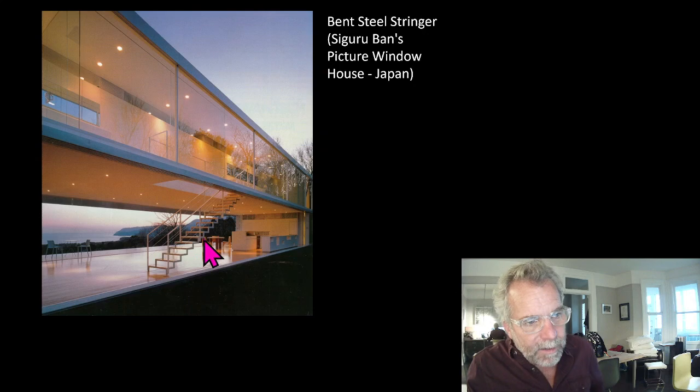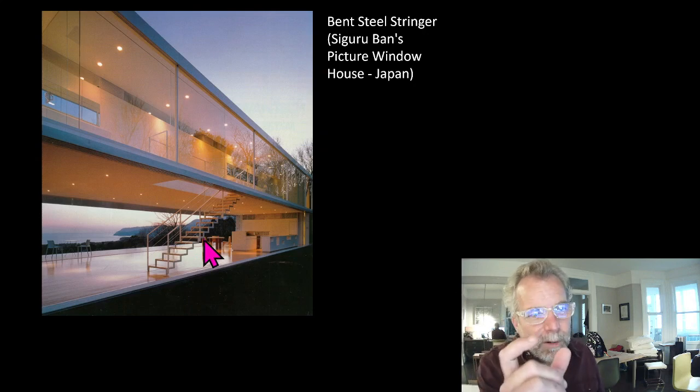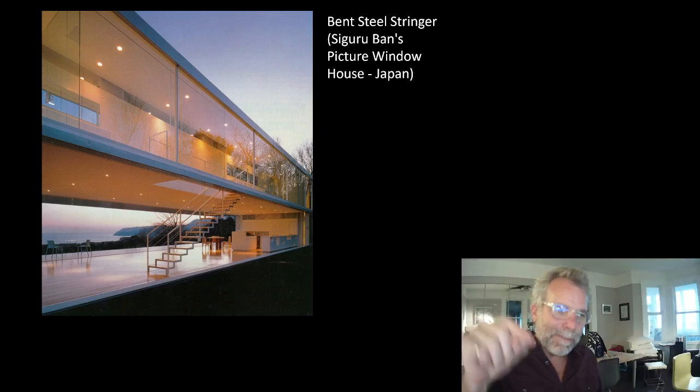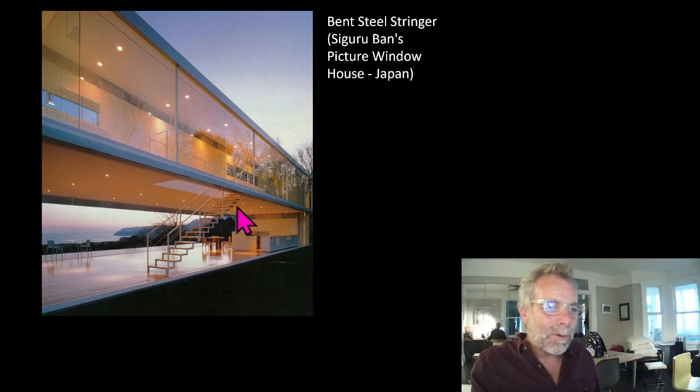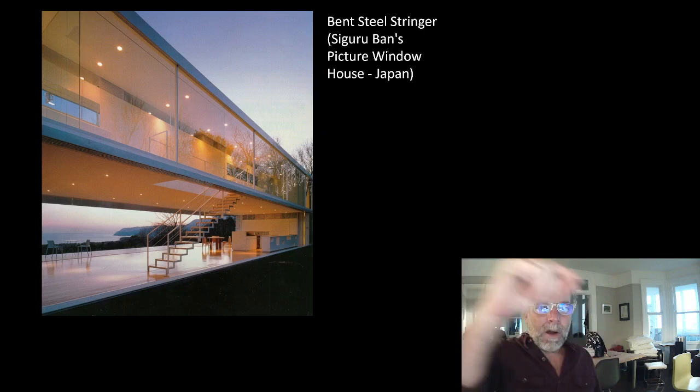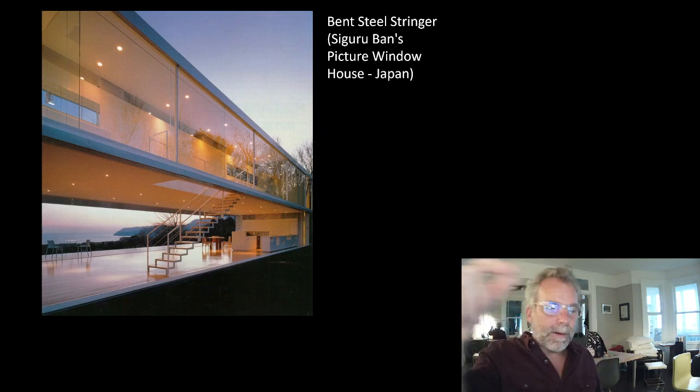I did the calculation and found that if the stringer was 60 millimeters thick, it would deflect 200 millimeters at mid-span. It's so flexible. So in that case it was strong enough, it was just so flexible. We had them cut the plate on an arc, pre-cambered.